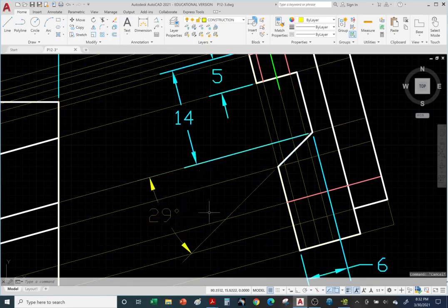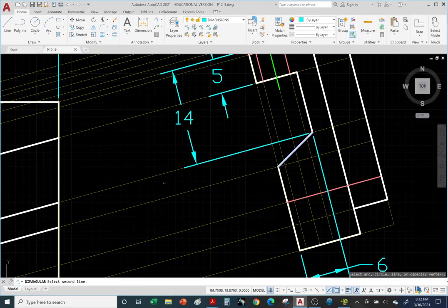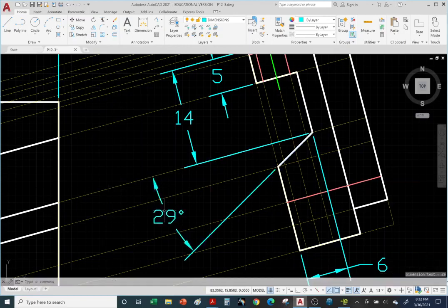All right, so let me start from scratch with this one. Do it over again. Let me delete it. Go to the correct layer. Somehow I got stuck in between layers. Do it over again. Okay, it's all right. It's practice, right? Let's go angular again, from this line to this construction line. There it is. Now click on the dimension and let's use this grip to, there it is. You guys see the extension line. Click. All right, this time it worked. Woo! We got lucky. Hit escape.